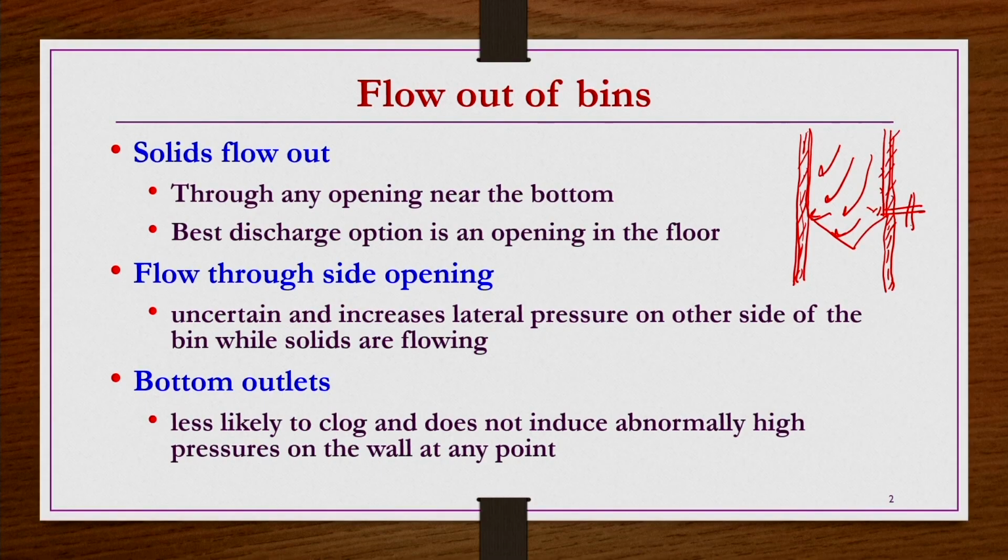Okay. So, these details of the pressure distributions, stress distributions, etc., we are going to see very soon now, but however, this is one of the reasons that you do not prefer to have a side opening. Bottom outlets are going to be better options because they are less likely to clog and do not induce abnormally high pressure on the wall at any point. So, here, if you have a side opening, then the pressure may be low on this particular wall, but on the other walls the pressure may be very high.